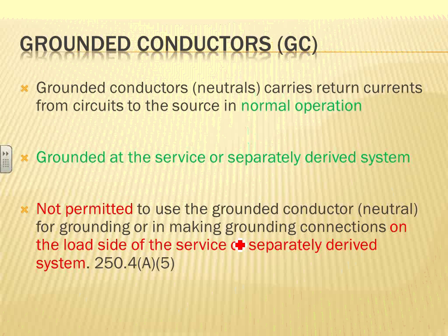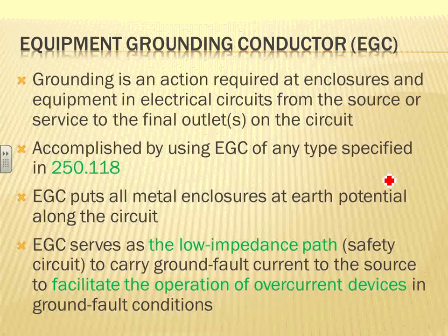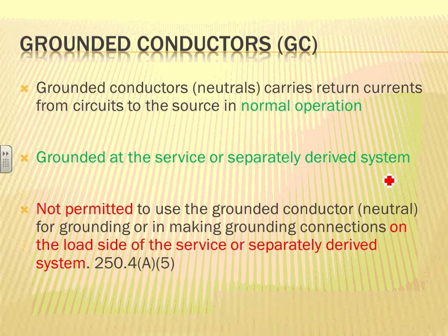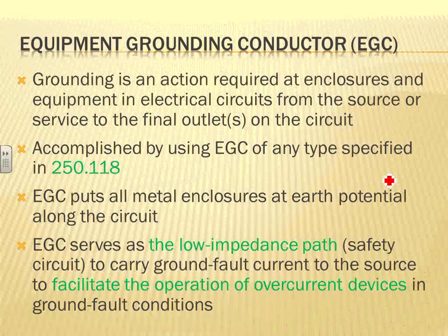If you ground them through the neutral, then you take a chance that under normal operating condition your equipment could be carrying current. So they used to do it with the dryers and ranges in the past, right? You ground the frame, no longer allowed. We'll talk about this one on the load side.